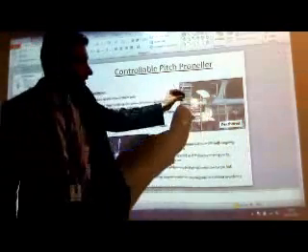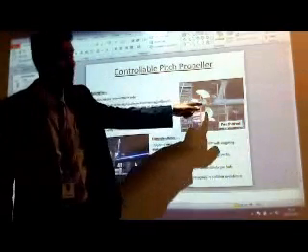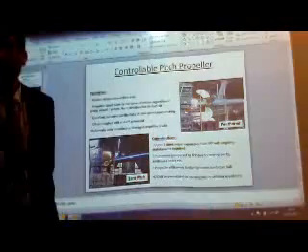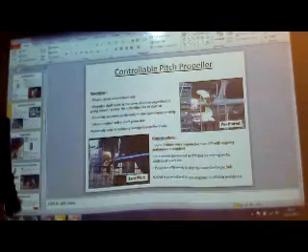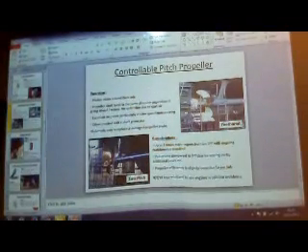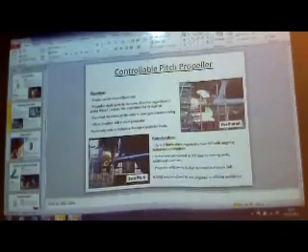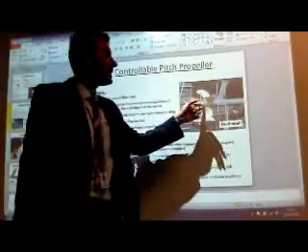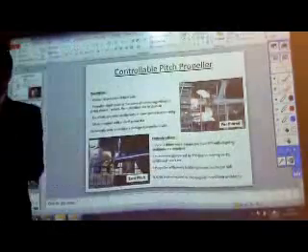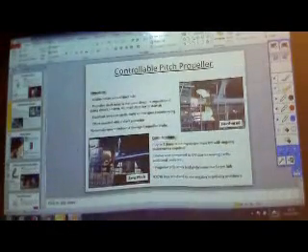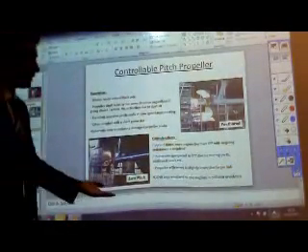The hub is the part that is behind a propeller. You see this extending part? That is called the hub. You need more devices in the hub to control the pitch angle of the blade, so you will end up having a bigger hub. This bigger hub will cause poor flow, and that will reduce the efficiency.